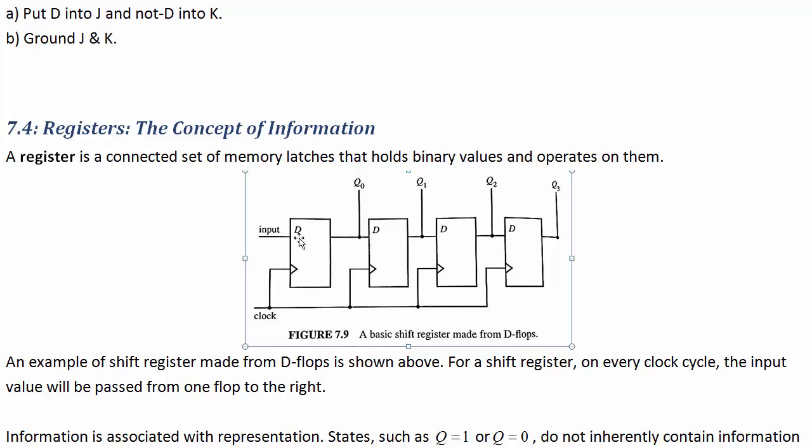As the clock goes high, it looks at whatever information is on the D, and then after some slewing time inside, maybe 5 milliseconds, it'll pass it over to the right. So when the clock goes high, this input looks at whatever was originally there and then starts passing that data over. If this changes at some point over the next 5 milliseconds, this flip-flop doesn't care. It's going by the input it had as soon as the clock went high, which is what this output was. Similarly for this one and this one.